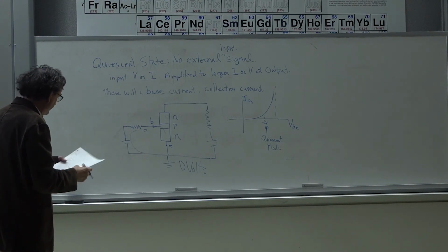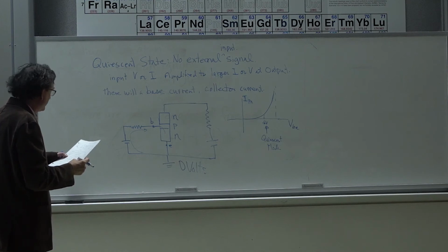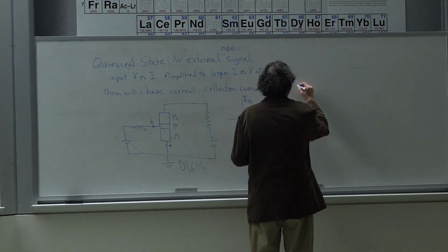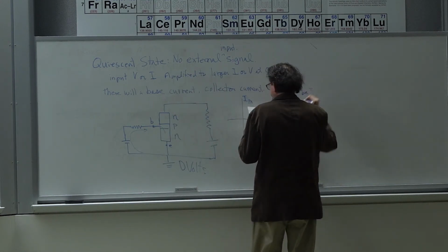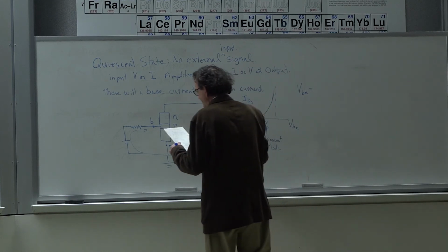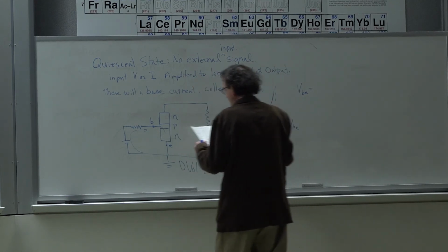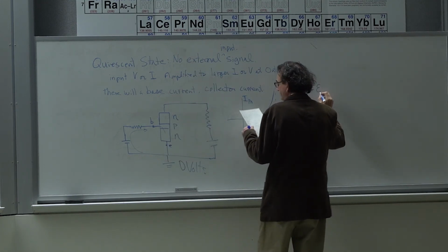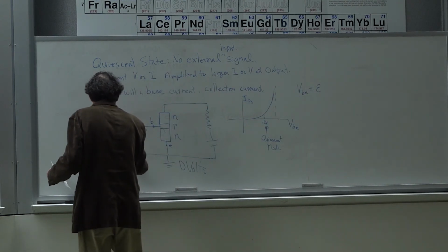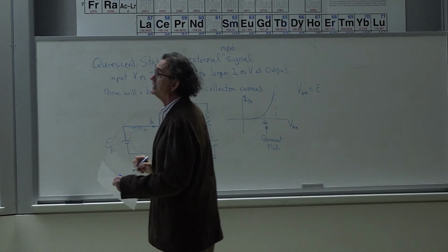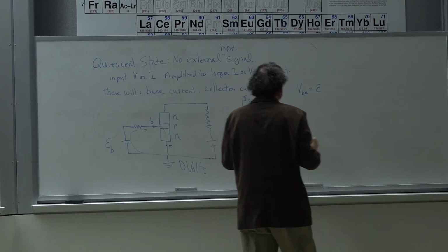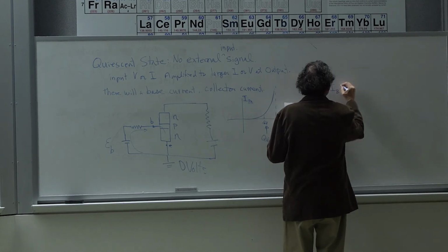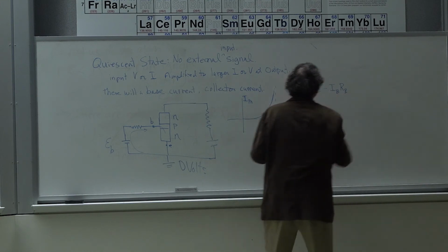Now, that is one of the most important key points. So now what I can do is say that I can write an equation for VBE. VBE is equal to, using the circuit law, the voltage labeled epsilon sub B in the figure, epsilon sub B minus the IR drop across the base resistor. So we'll call this IB times RB. Okay?